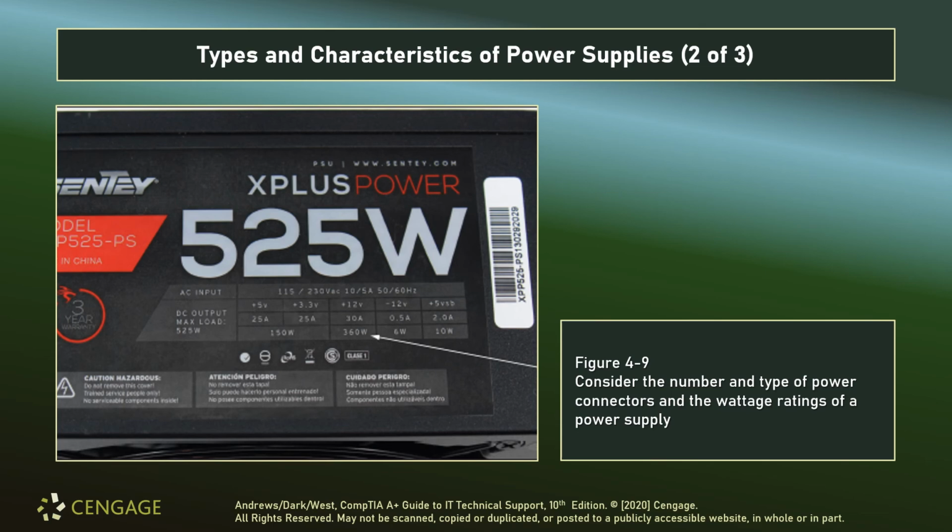Your 12-volt rail can run at 30 amps in this case, 360 watts total. The negative 12-volt rail only runs at half an amp and can run at 6 watts. And then we have what's called the plus 5 VSB, 2 amps at 10 watts.